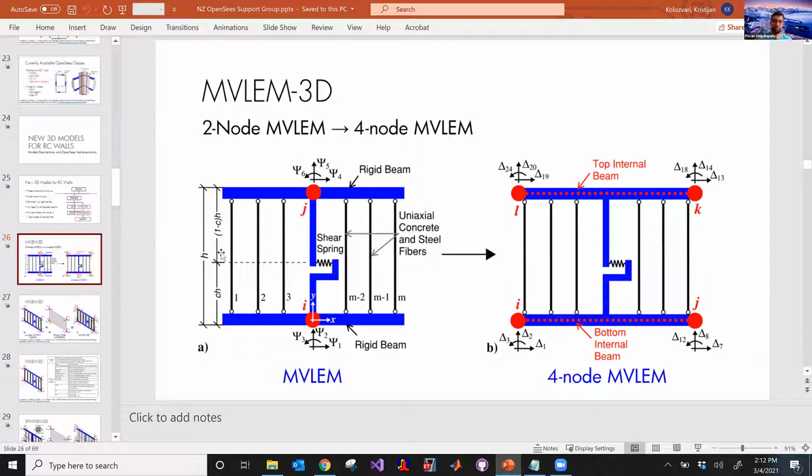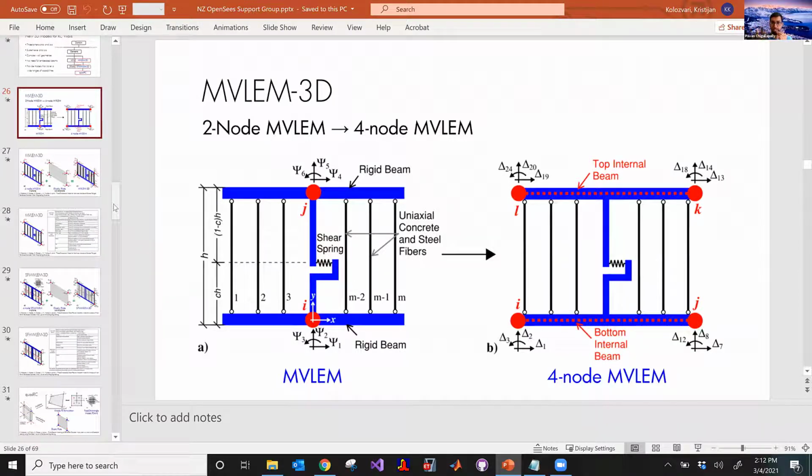Traditionally, OpenSees is better at modeling the global responses of structures, not the cracking and spalling of concrete, because it's a macroscopic element, as you said. But these models are able to address some of those issues, but not all of them, right? That's my understanding.